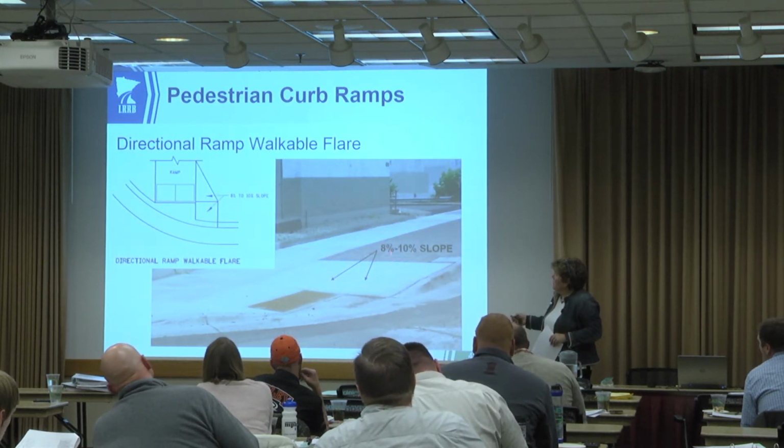When you have the walkable flare, depending on if it's an area that you expect people to traverse over to get down to the ramp, then the maximum slope is 8 to 10%.